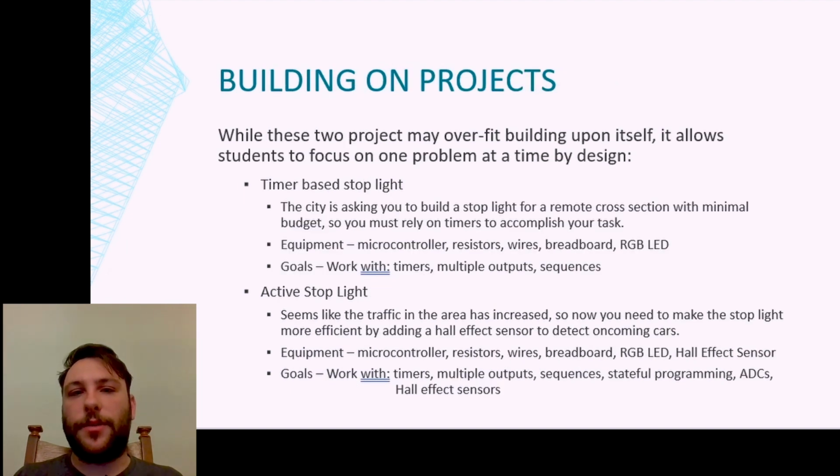So let's talk about building on projects. And while these next two projects might be an overfit, it allows students to focus on one problem at a time by design. The first one is a timer-based stoplight, where you just have a time-based stoplight system. The only input is the timer. You don't have any sort of sensors. So the equipment for this is a microcontroller, resistors, wires, breadboard, and RGB LEDs. And the goals for this lab are to work with timers, multiple outputs, and working with sequences.